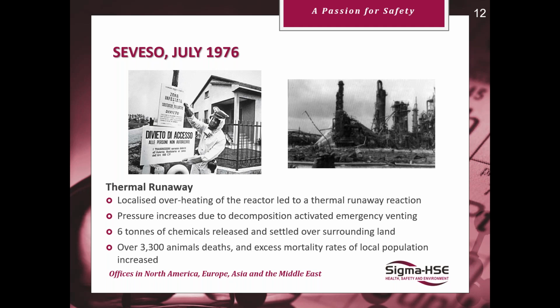We'll go through later some of the common causes of runaway events. So we had the out of process occurrences here: the higher temperature, stirring was ceased, and there were also not the catches in place, such as there was no temperature reading available on the steam lines for the operators to see and react to.